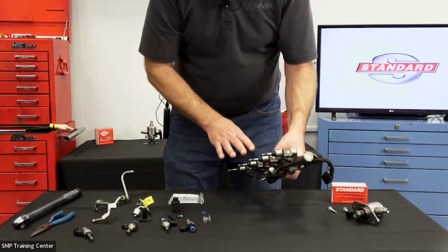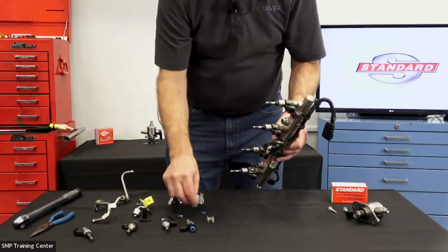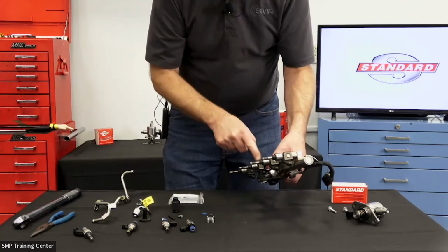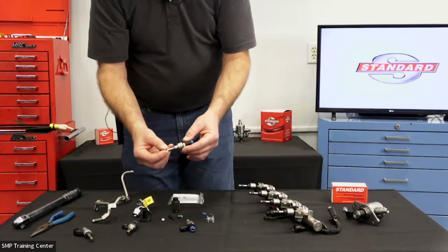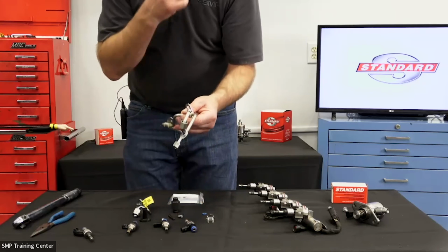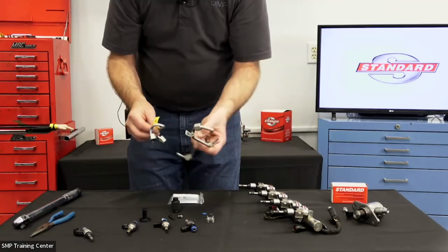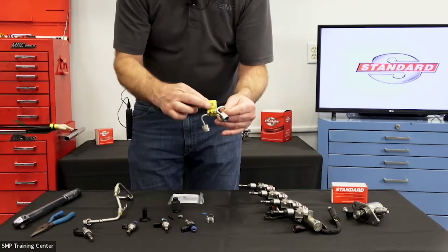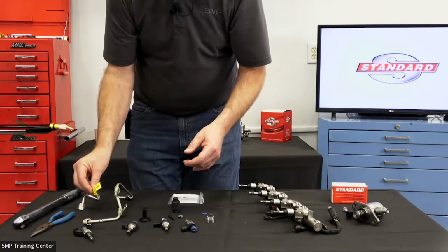But there's a tremendous number of one-time use components. If we did remove the injector from the rail, we would also be replacing a spring clip and any other seals and spacers that there are on the top of the injector. There is a seal here, and there is a spacer here on the top of the injector, as you see on this example that I have right here. There are also some other one-time use parts. We would be concerned about perhaps any high-pressure lines. High-pressure lines are going to be something that would be just one-time use. Once you take it off, you do throw it away and you replace it. Some manufacturers, like GM, even use a yellow tag on these lines just to remind you that if you take this thing off, you're going to have to replace it.